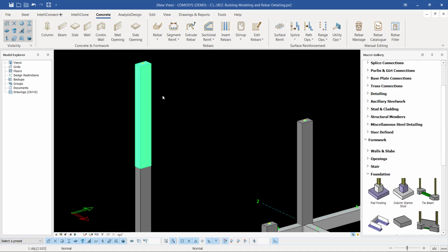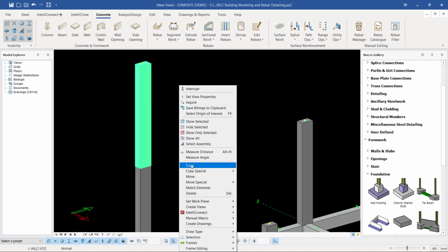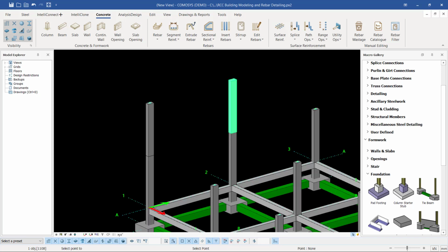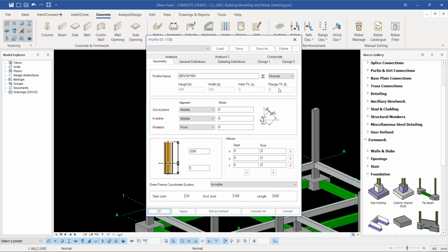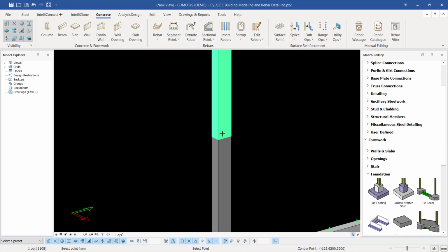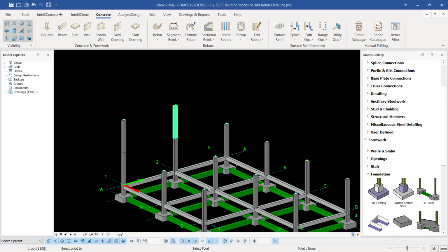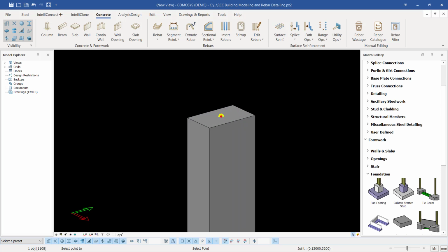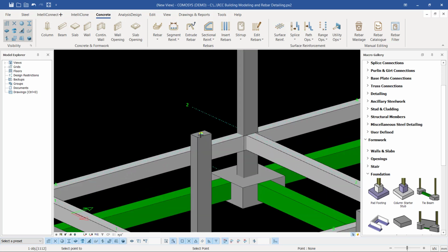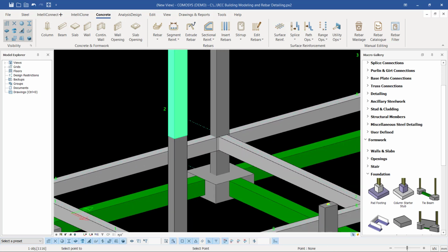If I select on that, right click and come to copy, then snap on that end and snap on that far end, you can see from a distance there's some change in our dimension, though it is not. So I right click once again and pick it from this spot. Always when you're doing the detailing, make sure you're doing everything accurately. The moment you suspect any variance, just go back immediately and rectify.